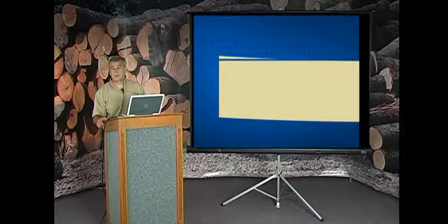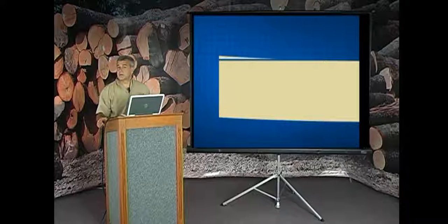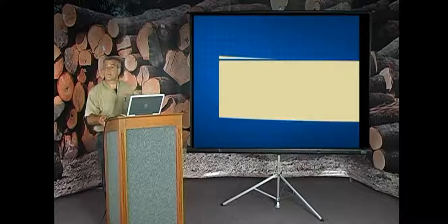There's no substitute when you're framing up a building for accurate lumber. You double your plates on the bottom and double your plates on the top. So the risk is that your walls are a different height, a considerable amount, if your lumber varies. So it's very important that your thickness remain consistent, that it's all the same, and that a builder can use it and calculate the height of his walls and so forth, because the lumber's accurate. He's stacking them on top of one another, potentially, for plates and sills.